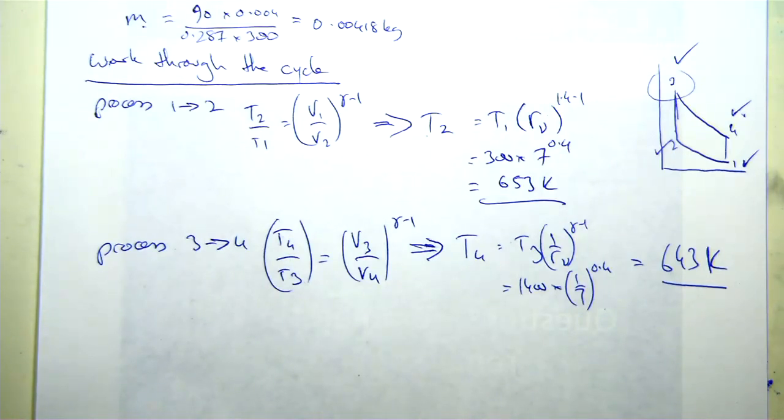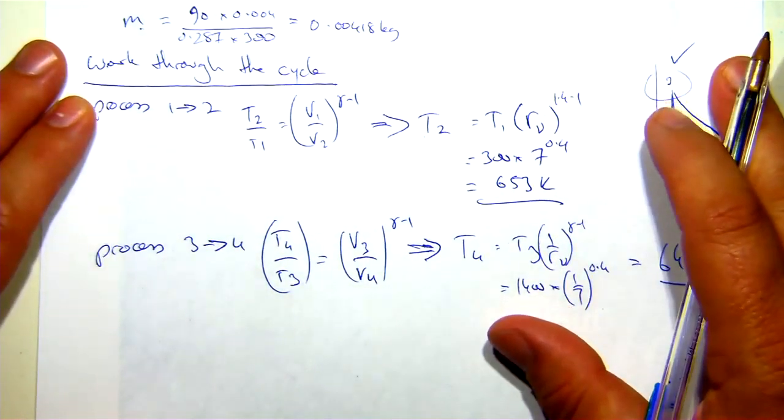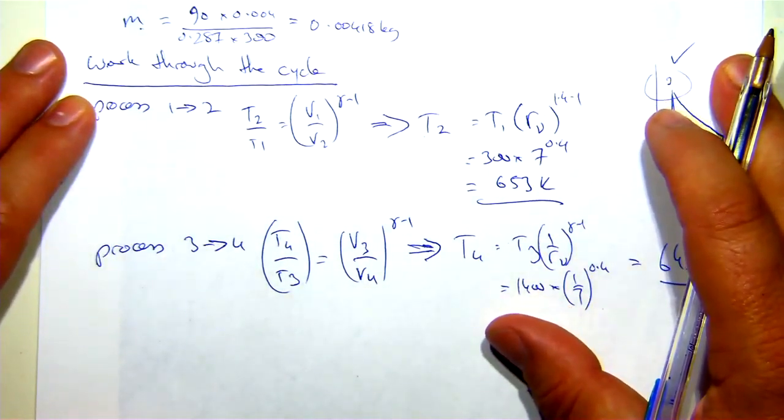So all I did there was use my equation for an isentropic compression or expansion, or an isentropic process, to determine the temperature after the process. I've got geometric information about the engine, and I use the ideal gas, cold assumption, isentropic process to get to the next point of that. That's finished mapping, so now I look back at what I'm trying to solve for and try to decide whether or not I can solve for it.